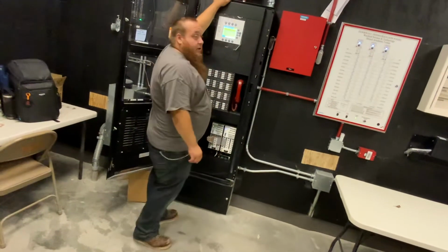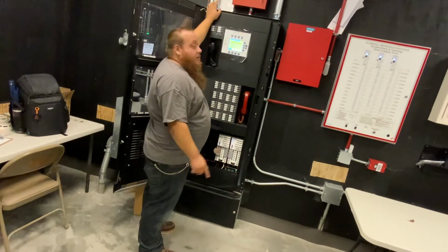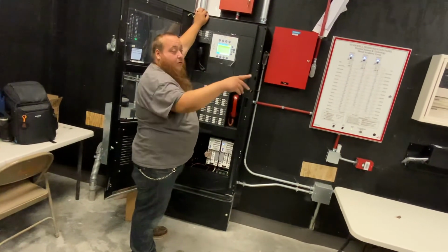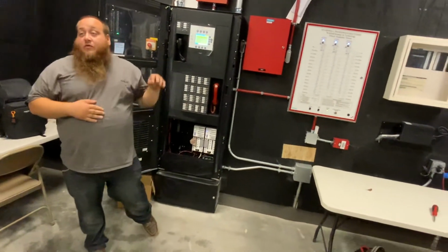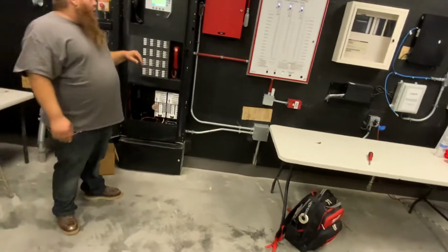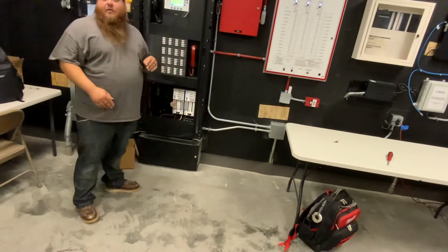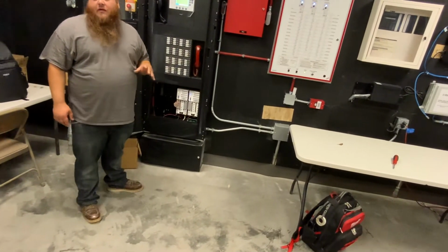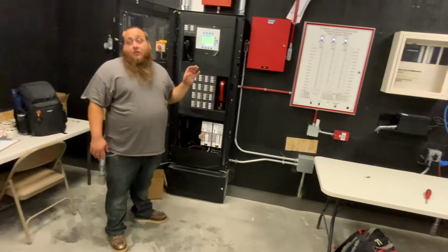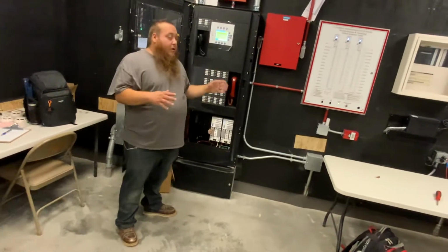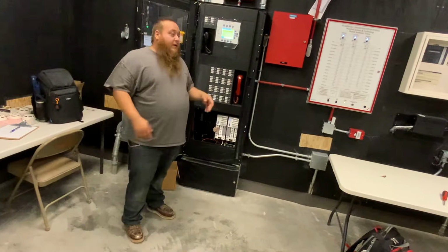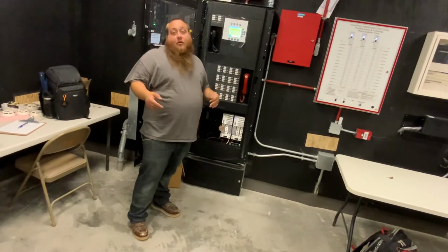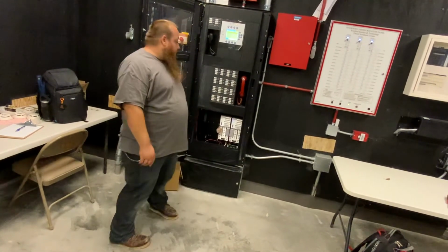This is your dialer here. We put a spare piece here, and there's also a piece of paper on the wall there for the network, the phone number, the account, and the password if you ever have to put the system on test. If there's any construction or anybody's working in the building, you should always put the system on test and call Philly. Because sometimes people walking by, they hear the noise, they call. And if you call Philly, you'll avoid false alarm, things like that.